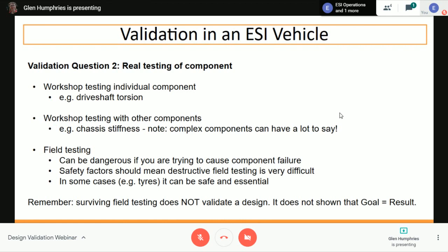One way you can do this with the chassis is to take something like a broom handle, basically a long, rigid length of wood or steel, and strap it rigidly across the chassis. You've already got one across the front uprights, the front hubs. So put another one at the front of the driver's window, say where the pillars come down to the side rails. Another one at the back of the driver's compartment, across where his back is, and then another one at the very rear of the chassis.